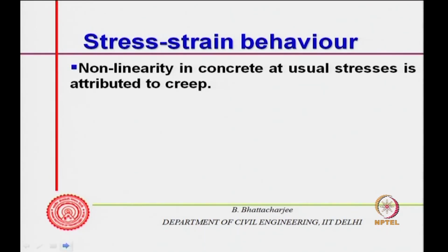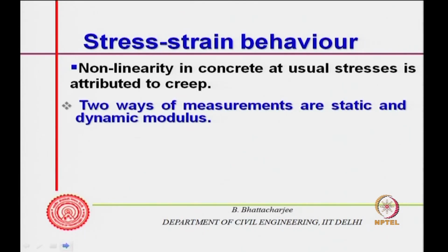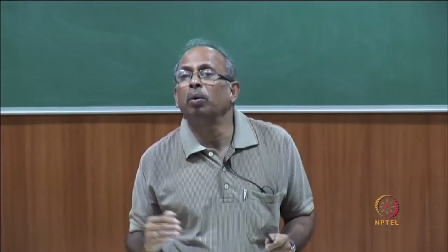Now, if you look at stress strain behavior, it is nonlinear, that is what we have shown, and this is attributed to something called creep, that is the deformation under sustained loading. We will come to that sometime. It is one way of looking at it, but there is something more we will look into. We can measure this under static condition, another is under dynamic condition. Static condition means you apply the load monotonically in steps and then see how the strain changes.